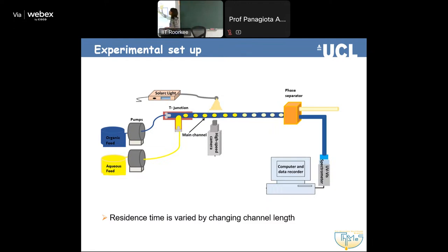Okay, so we are not going to reach equilibrium. And actually, if we want to do experiments in the lab, we avoid equilibrium, because then it's very difficult to see the effects of properties, if you see what I mean. If I want to see the effect of concentration and everything reaches equilibrium, I'm not going to see it. So I really need to be a little bit before equilibrium, so I can see if I change my flow rate ratio, my concentrations, how do I affect the mass transfer?